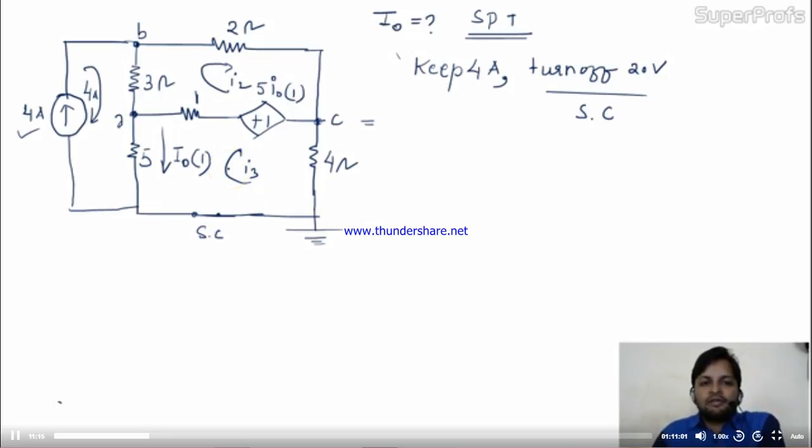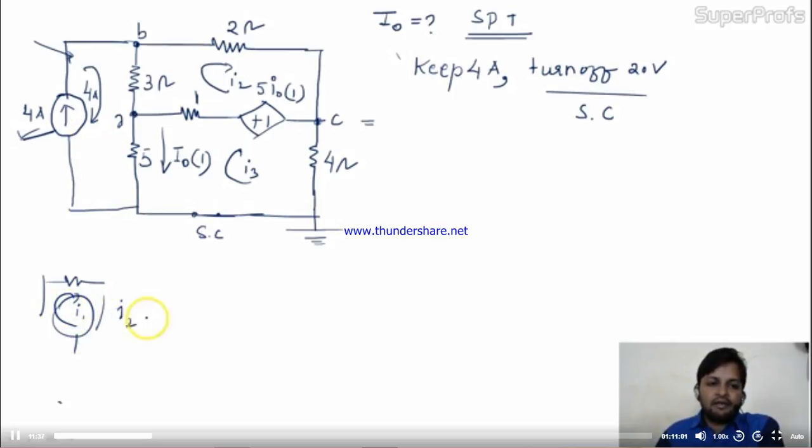Once we solve this circuit and write the equations, there is no need to go for this mesh. Why? Because we already have the mesh current. While solving by KVL, we assumed I1 and I2 and I3, right? Here we have 3 meshes, but for one mesh I have the value of I1, so the remaining variables will be only I2 and I3.